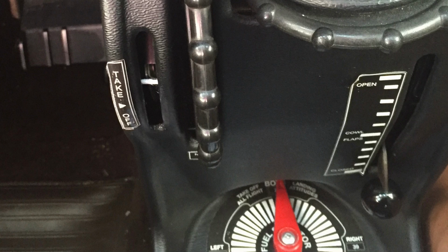The concept here is that the cowl flaps are open when you're taxiing and when you're taking off and climbing up to altitude. When you get to your altitude, then you close the cowl flaps while you're en route and when you're landing. After you land, you open the cowl flaps back up again. That gives you the most cooling when the engine is the most stressed and the least amount of air is flowing through the engine.